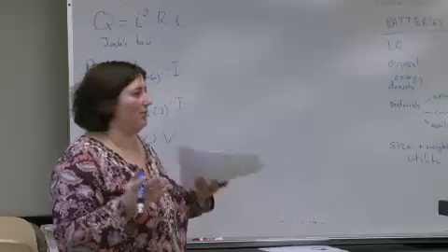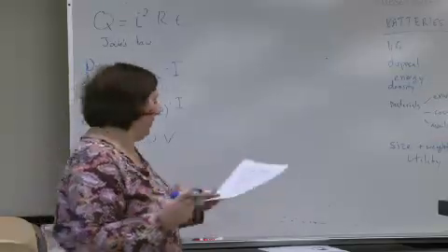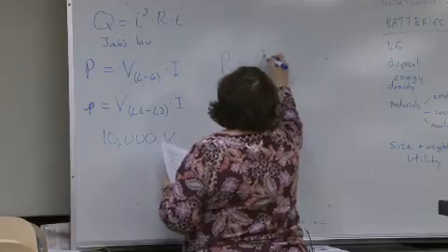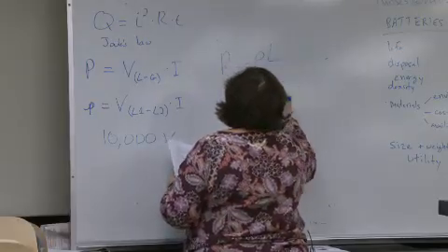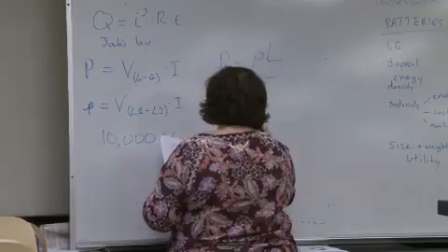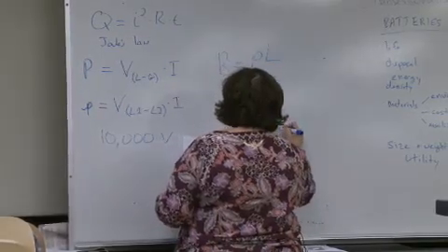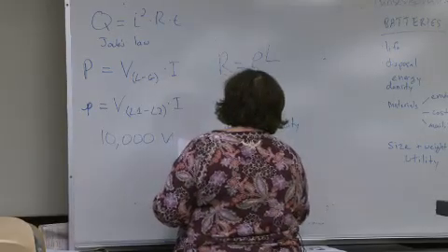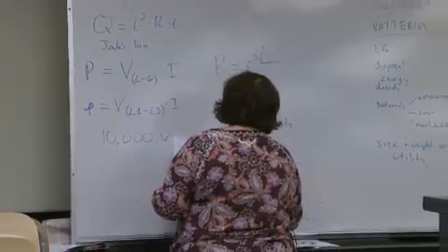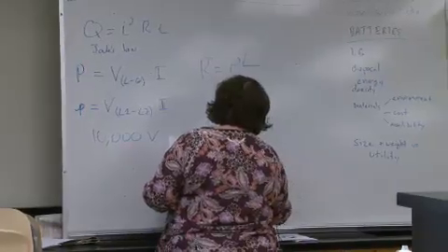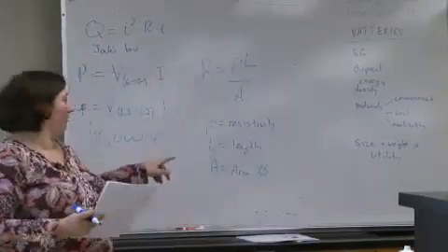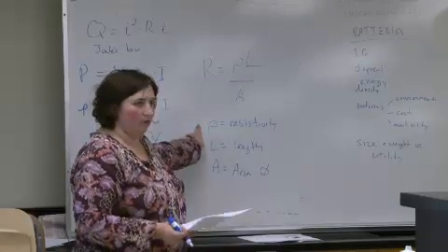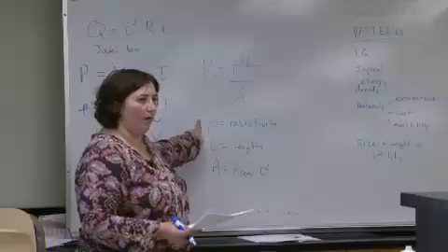You already answered it. It's the resistance in the wire, right, is what we have to worry about. So the resistance in the wire is based on rho L over A, where rho is the inherent resistivity, L is the length, and A is the cross-sectional area of your wire. And for your resistivity, that means you're picking your wire. So you could use an aluminum wire or a copper wire or what have you.